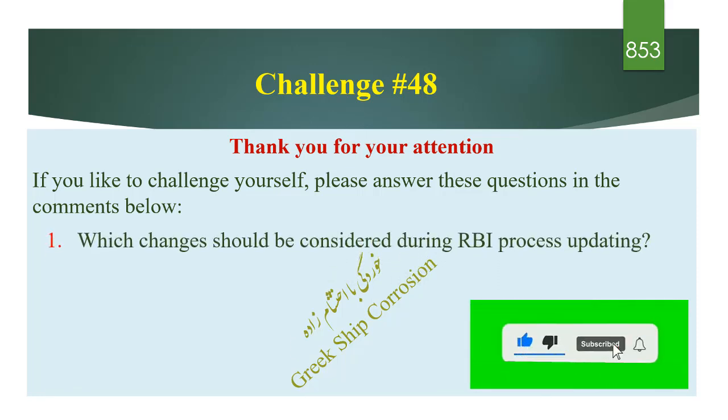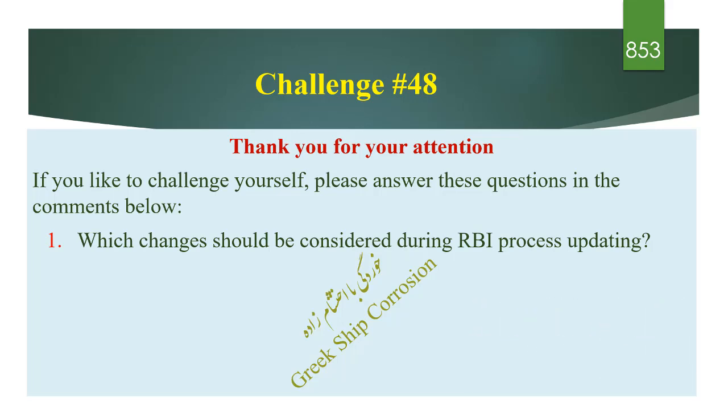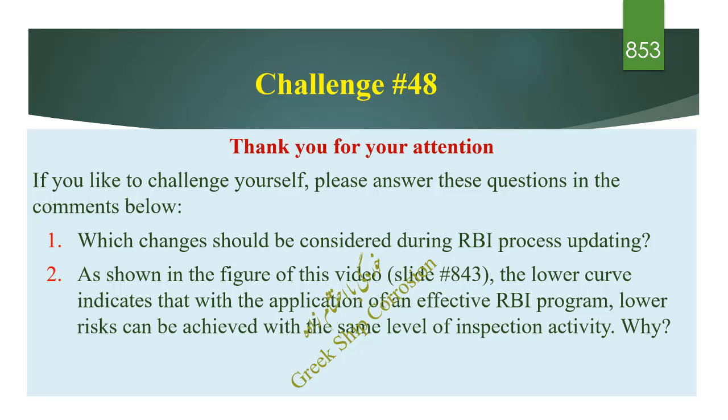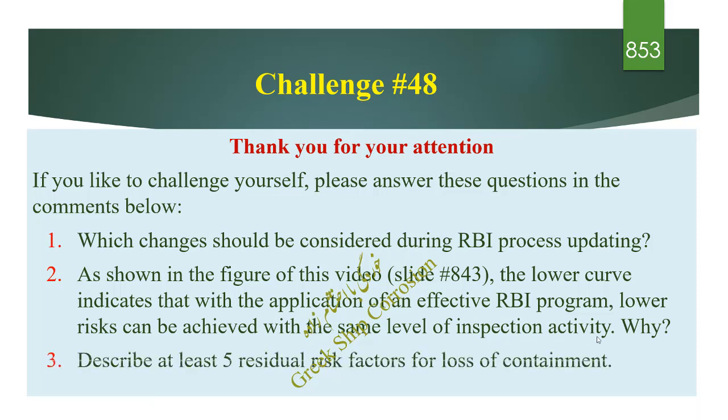1. Which changes should be considered during RBI process updating? 2. As shown in the figure of this video, slide number 843, the lower curve indicates that with the application of an effective RBI program, lower risks can be achieved with the same level of inspection activity. Why? 3. Describe at least 5 residual risk factors for loss of containment.